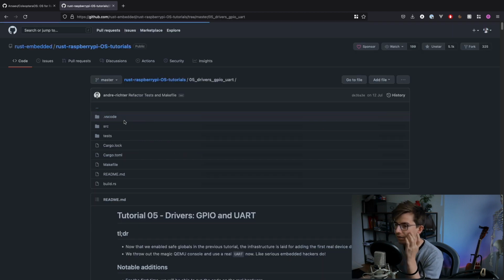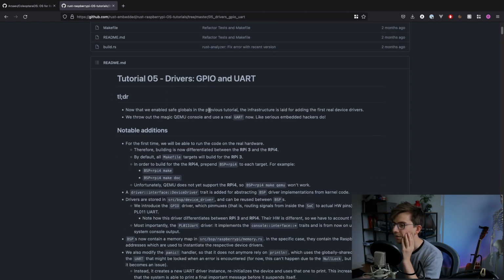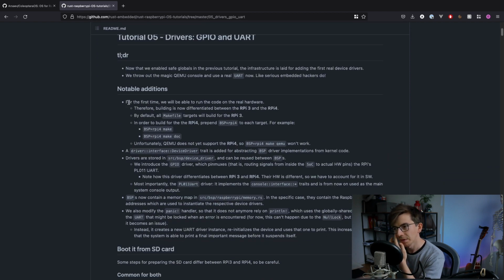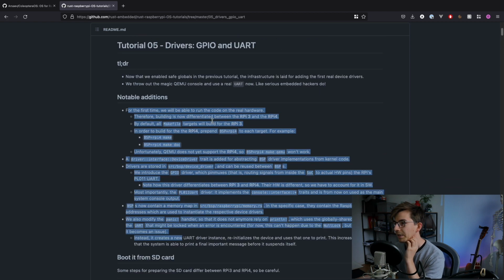And in this video, I will cover what tutorial number 5, drivers, GPIO, UART, offers us. Unfortunately, except for this small description, there is not much explanation of what the code exactly does and how it works, except some rare comments, so most of the understanding you have to do by yourself. Read this code, read some reference materials and try to understand it. Basically, what it does is throw out the magic QEMU console and use the real UART interface now.